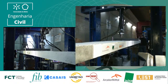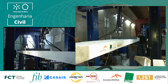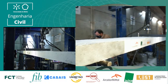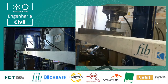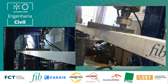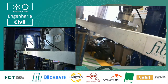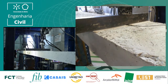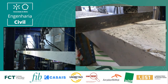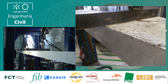So we see here one of the loads in the sagging region, and the other loads, and we have LVDTs that are measuring on the other face of the beam. We are measuring the deflection. We have installed in the top part strain gauges to measure the compressive strain in the fiber reinforced concrete, in both hogging regions.